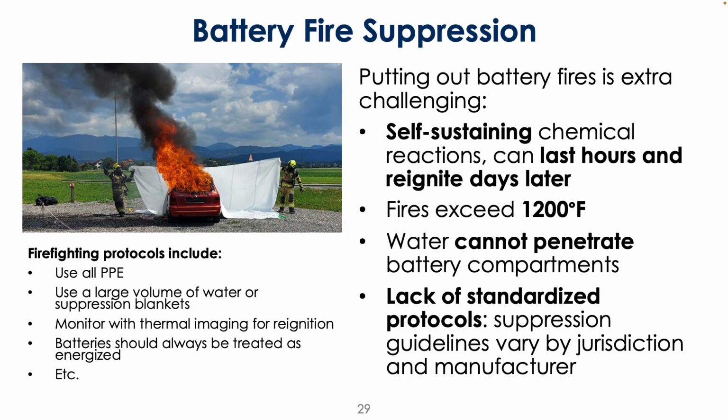Battery fires are particularly challenging. Now EVs are widespread enough that there are well-developed protocols for a lot of firefighting units to be able to handle this, and they do have pretty specific procedures in the way that they fight battery fires. So you have to use PPE, you have to use suppression blankets, and after you put the fire out, you have to continue monitoring the battery for some amount of time because it can actually reignite if the thermal runaway continues to happen.